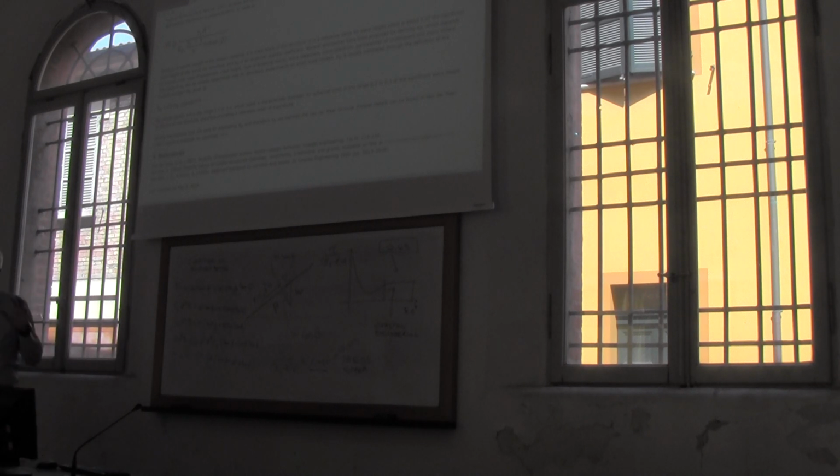Okay, so let me just make a summary. We approached with a very empirical approach the design of groins. First of all, we studied in the previous lecture how to design groin spacing and length according to the 1/3 rule. And therefore we learned how the profile of the beach is modified by the presence of groins. And then we also discussed permeability and bypassing.